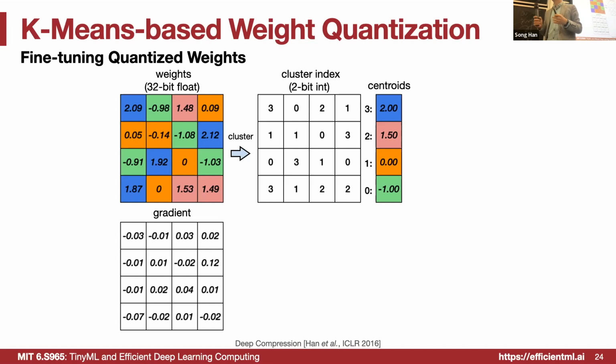Okay, I have one more question. Why can this method get speedup? Because in matrix multiplication, every time we want to get a number, it's an indirect address. We need to get the index first and then index it in the codebook. So you have to access memory twice to get one number. Yeah, so this requires specialized hardware support. This is not in the main memory, but you can put it in the on-chip SRAM, since this is a pretty small codebook, right? Which can be completed within one cycle to access 1 out of 4 numbers.